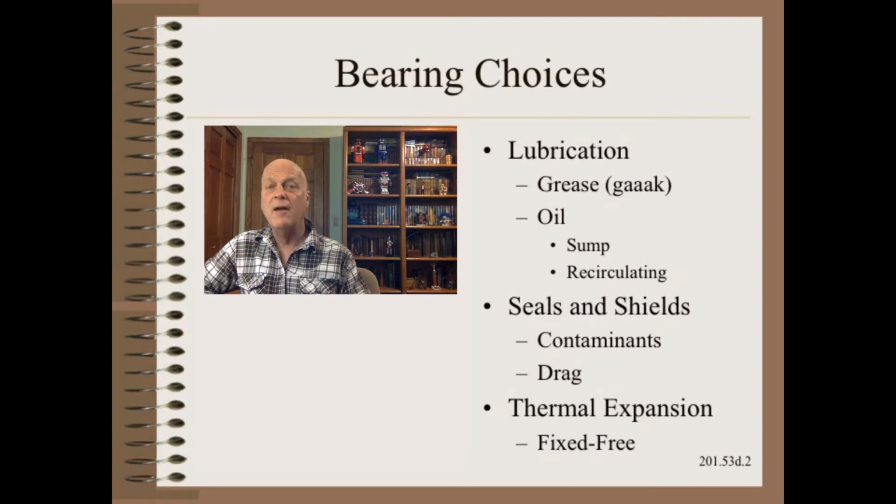Some cheap idler rollers have free bearing mounting styles. Process rollers, on the other hand, are usually fixed on the back side and free on the front. Also, make sure that your maintenance people assemble the bearing in the correct part of the travel within the housing. If the roller will be running in a hot process area, the cold assembly will be with the free bearing near the inner limit of its range. Also note that thermal expansion makes bearing fits and clearances extremely challenging.